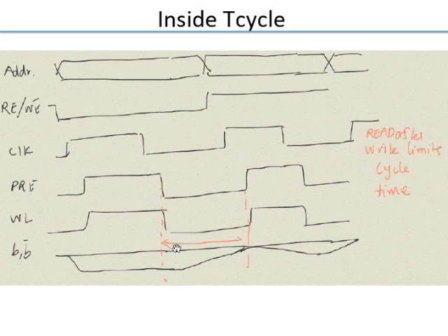So when you finish the write, and you can only finish after the word line is low, that is when you start pre-charging back the bit line, and it has to be ready by the time the next word line goes high. Remember what I said, that suppose the next time you're reading a memory cell, the row from which you're reading has a value which is opposite to this value.